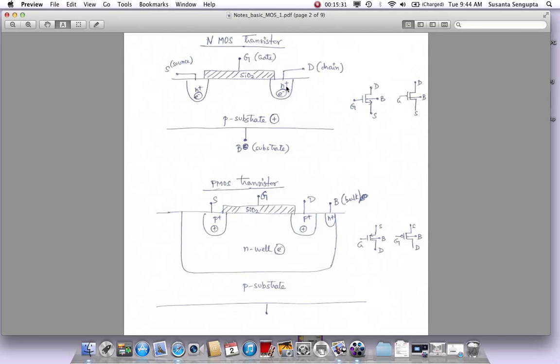These are heavily doped now. As we talked about, these are heavily doped with N-type material. So these are very heavy in terms of electrons. So you have P substrate here. This is all P, but here you have a heavily doped N plus, heavily doped N plus. Okay, and on top of it, with a little overlap, which is always there, we can never avoid it, we grow the silicon dioxide. This is an insulator grown on top of the substrate, and on both sides heavily doped N plus regions. And there are 4 terminals that we need to understand of a MOS.